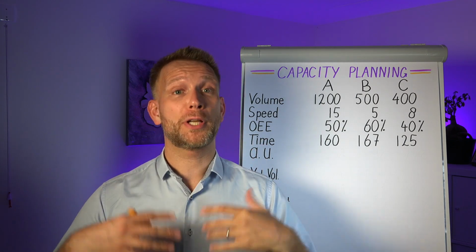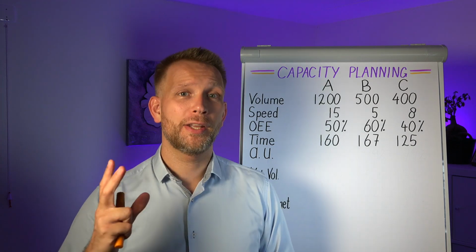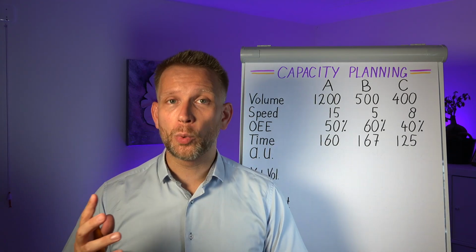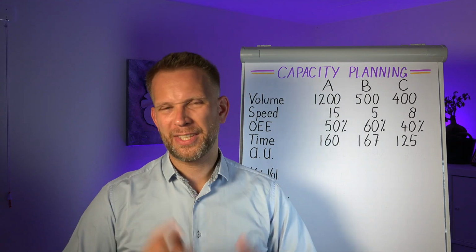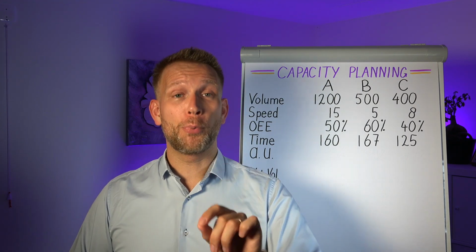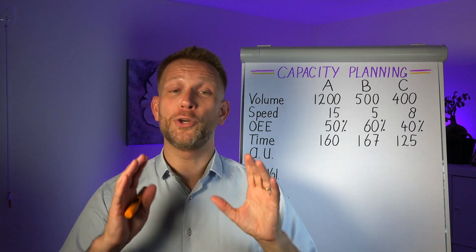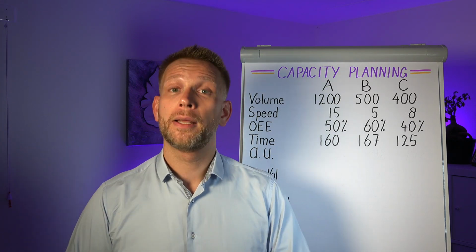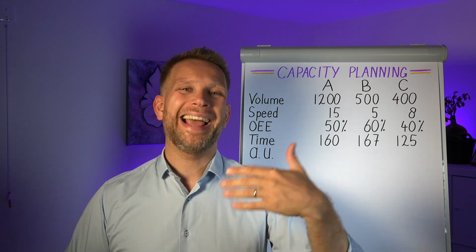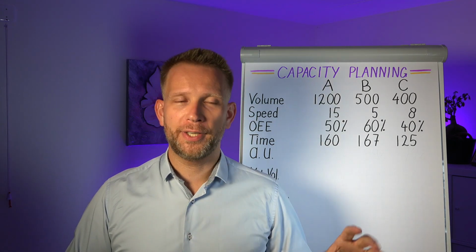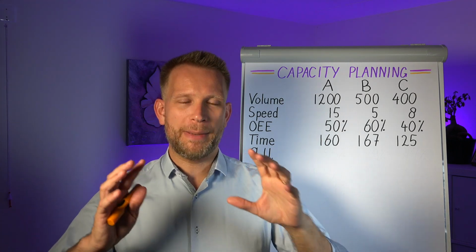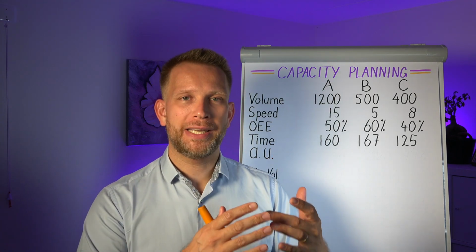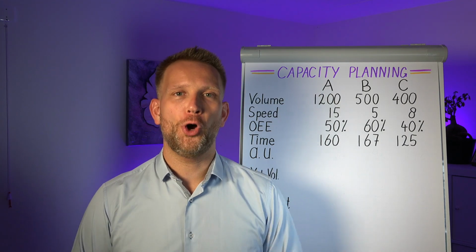And now it is really about capacity analysis, not just OEE, but what does that do to our plant volumes? Do we need to work on OEE somewhere, or is it just to decrease cost a little? Super important things to know, especially in your budgeting cycle or when you're making your strategic planning for next year, your annual operations plan, but a good thing to keep in mind at any moment when you are prioritizing your focus improvement teams or other improvement efforts that are aimed at improving the OEE, decreasing the downtime on your lines.